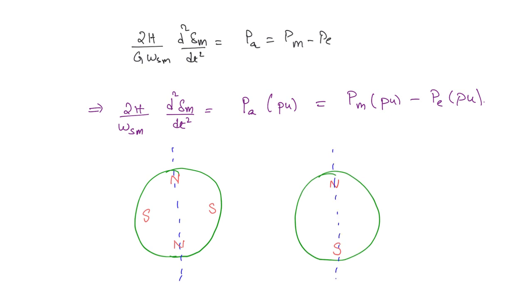What is going to happen if this point we will take as point A. Now what will happen in one full rotation in 360 degrees? This point A, it will move like this and then come back to the same position. Now that is 360 degrees in mechanical terms. In electrical terms, what will happen? If this point has come from north pole to south pole, it is 1/2 rotation, and then again from south pole to north pole, it is 1 full rotation, right? So here there is no difference between mechanical and electrical radians.